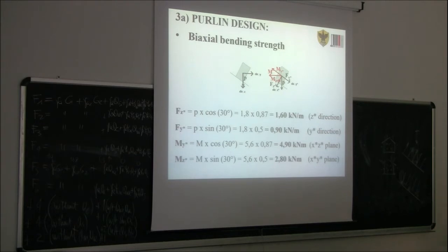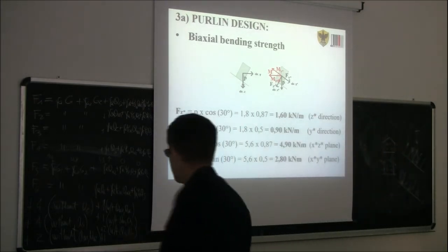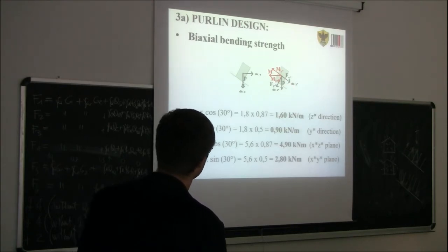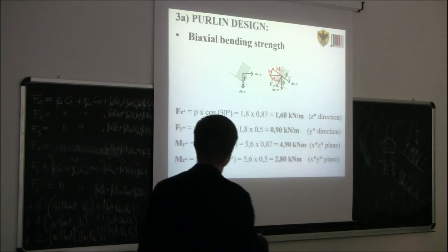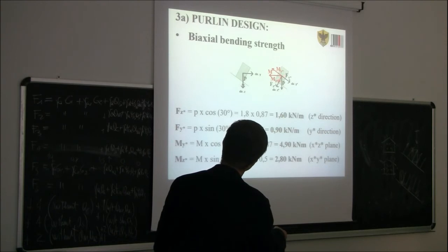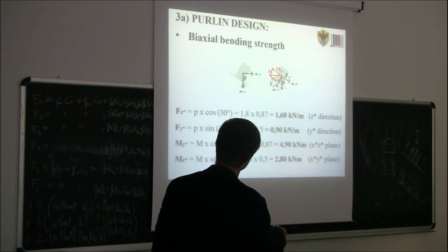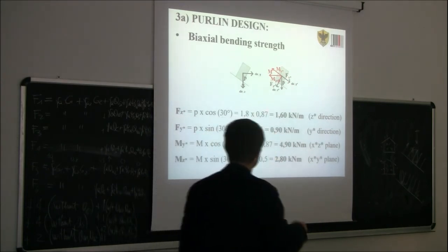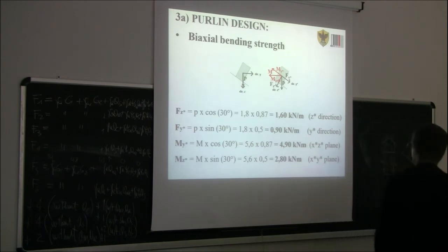So we can decompose directly the bending moment, so this biaxial bending, by superposition into simple bending, one around the y asterisk axis, which is what we call M_z asterisk, and the other one around the z asterisk axis. The M_z asterisk bending moment has y asterisk as its neutral axis, while instead the M_y asterisk bending moment has z asterisk as the neutral axis.